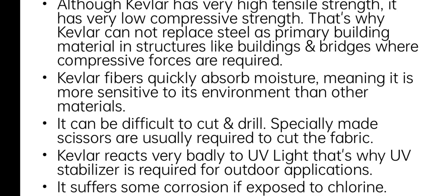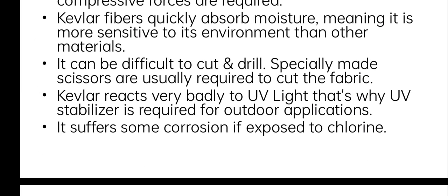Kevlar reacts very badly to UV light. That's why a UV stabilizer is required for outdoor applications. When we want outdoor applications, obviously there would be UV light exposure. Therefore, a UV stabilizer will always be required. It suffers some corrosion if exposed to chlorine. When it is exposed to chlorine, it can't resist corrosion. It suffers some type of corrosion when it is exposed to chlorine.